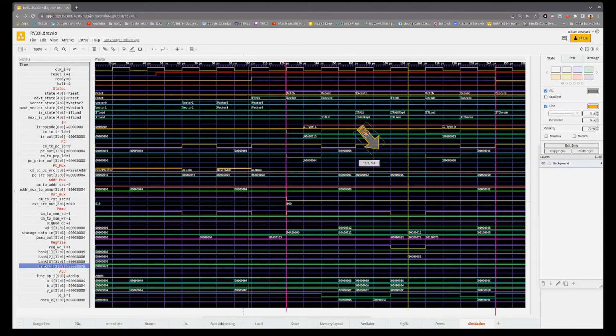We then transition into the ITALU complete state, which is our write back state. And as we expect, the register write signal goes low, and we write into the destination register, which is X2, the value 32. Excellent. This instruction is doing exactly what we were hoping it would do. And of course, it then falls into the e-break instruction and goes into the black hole of forever. And there you go. That's the ADDI.